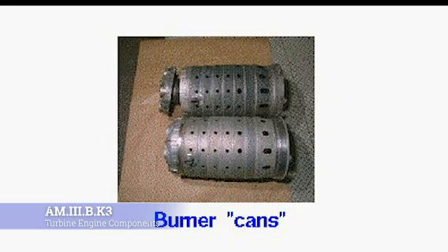A can type combustion chamber is typical of the type used on turboshafts or APUs. Each of the can type combustion chambers consists of an outer case or housing that has perforated stainless steel combustion chamber liners, or an inner liner. The outer case is then removed to facilitate liner replacement. So these liners will come and go as the engine gets worked on.